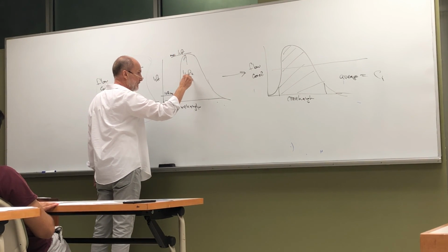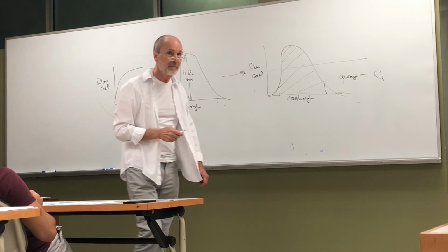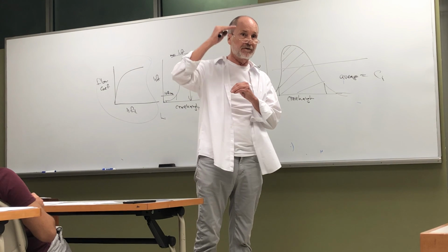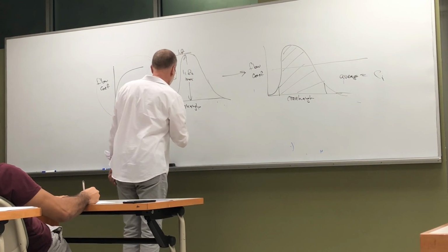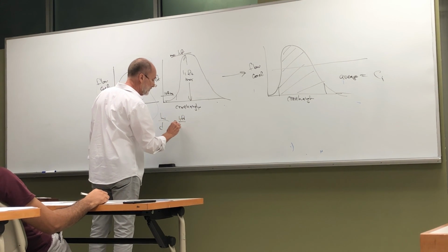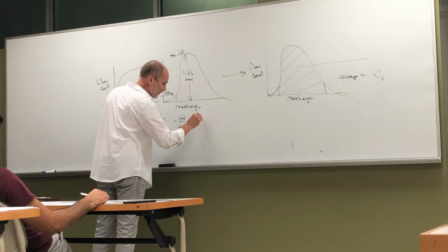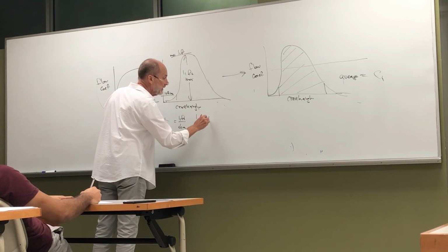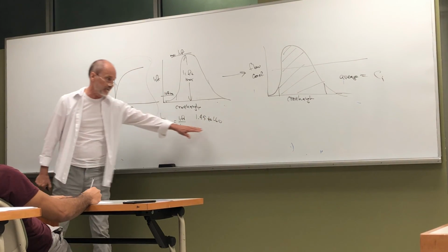Is lift the distance the valve opens? How do you define it? This is the lift of the valve: the most it's lifted, and you divide by the diameter of the head of the valve. Then you multiply, and it's somewhere in the range of 1.4 to 1.6. If you do a really super good job, you can get up to 1.65.